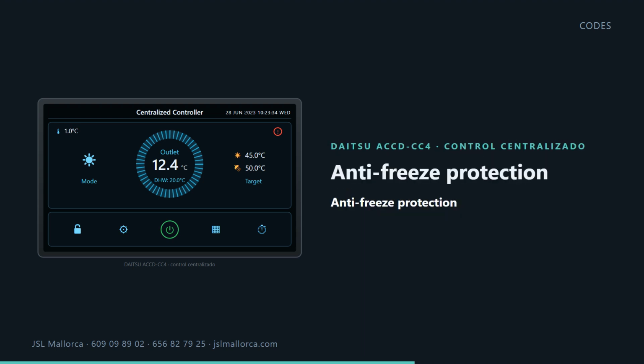These are protections against the water in the circuit freezing. They trip with cold outside and low flow inside. Them tripping means the unit is protecting itself, not that it's broken.